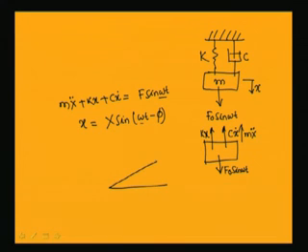And the damping force will be c omega X cos(omega t minus phi), so it will be at an angle of 90 degrees to the spring force, and its magnitude equals c omega X.